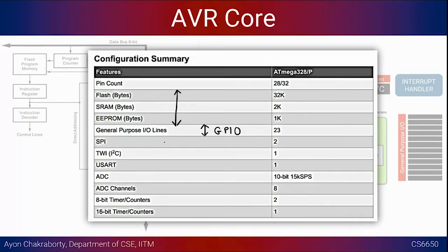And these are the peripheral interconnections, right? If you want to connect certain sensors. So these happen to have 2 SPI buses and 1 I2C, and this is for serial data transfer, ADC. So suppose you want a 12-bit ADC instead of a 10-bit one, right? Then you have to look at some other microcontrollers, maybe at higher ends. So if you really care about the resolution of your data coming in from analog to digital conversion, right? That we are going to study later.